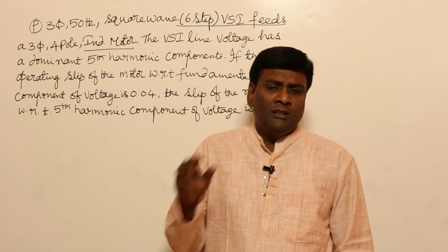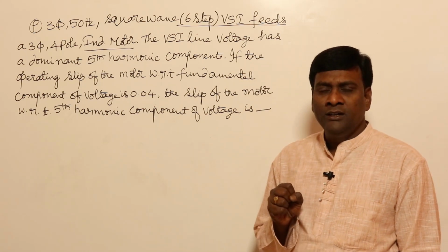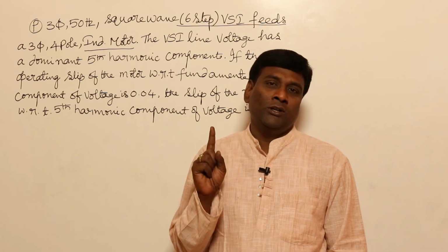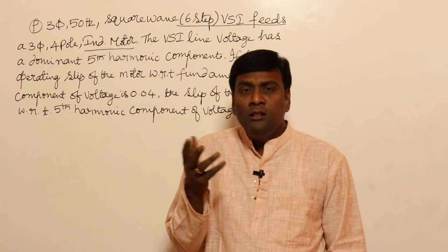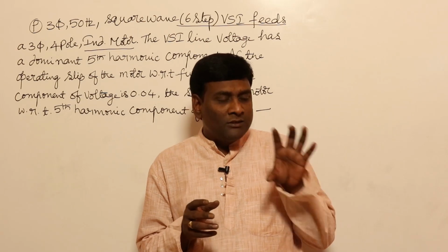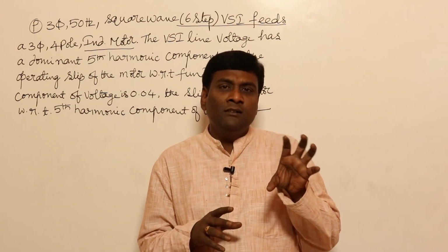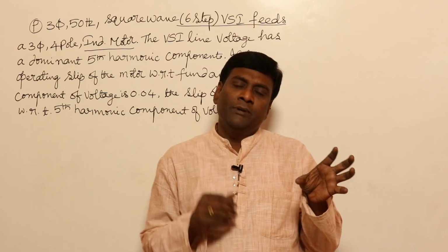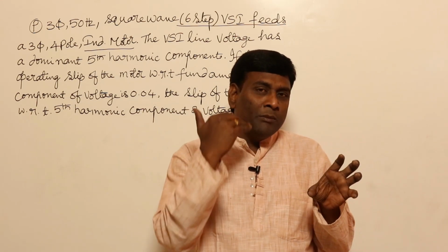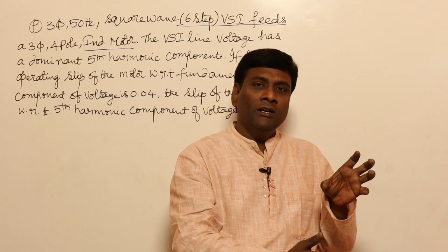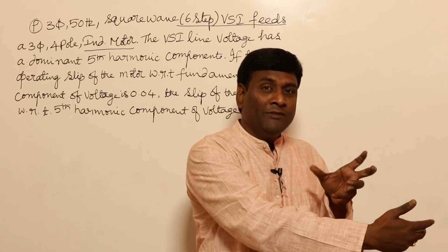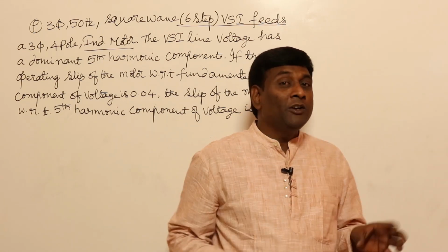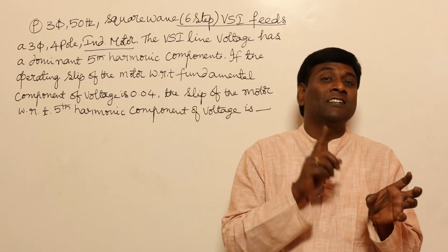So here we have to discuss many things. The first point is induction motor. Induction motor rotor will interact with all the harmonic components because, for example, the rotor is rotating at maybe 950 rpm. Stator mmf is rotating at 1000. So because of the 50 rpm relative velocity, induced voltages, currents and torque will be there or not?